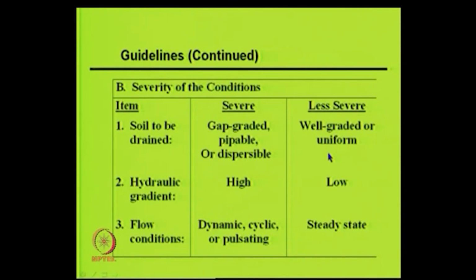But if it is a gap graded material, the problem is that water gets accumulated and there is a pressure, and then there is a possibility of damage. So, soil to be drained, this is a severe condition, this is less severe. And then hydraulic gradient, if it is going to be high, the condition is definitely severe, but if the hydraulic gradient is low, then there is no problem. Flow conditions, yes, if it is dynamic and cyclic, one should understand that properly.